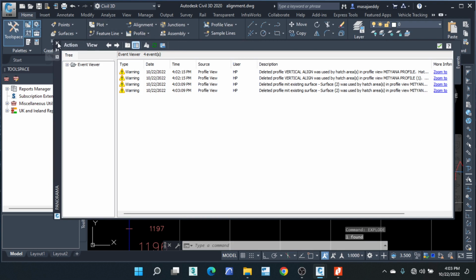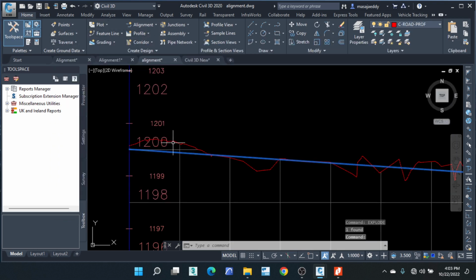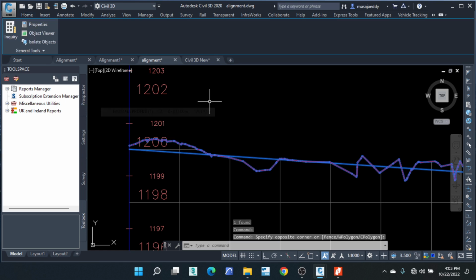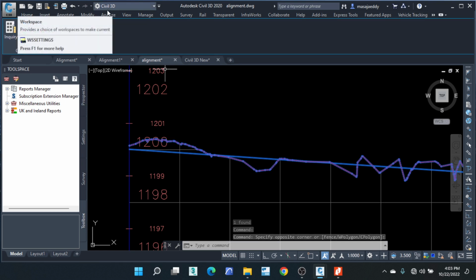I have a question about when I try to insert the minimum in the sub, it does not save it. It does not accept it. That means, because the K value is a function of the vertical curve, if the vertical curve can't fit between those tangents, it will not accept it. So you have to adjust the location of your PIs until you can get a curve that can give you a K value which is above the minimum.